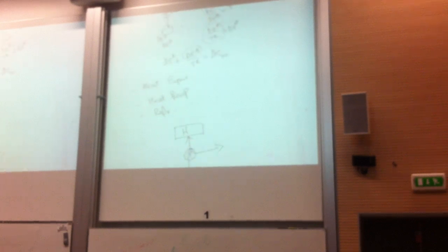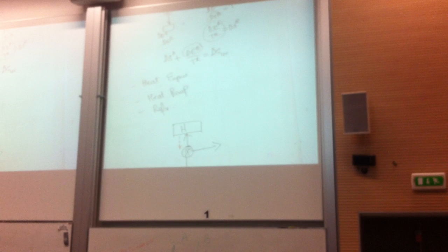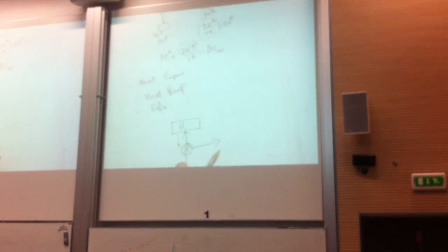You will do the same thing. Draw all arrows out, write down the energy balance, write down the entropy balance, and then see which equipment you are dealing with. If you are dealing with a heat engine, this is the direction of flow actually. The convention is you draw all arrows out. I have drawn them, but I know that this dE_H is that way, so I will write a negative with that. Work it out. I will follow the very same steps to obtain a relation for W_max and its efficiency.